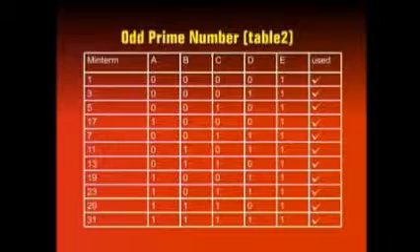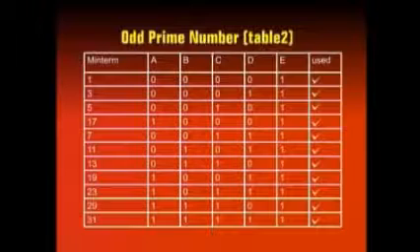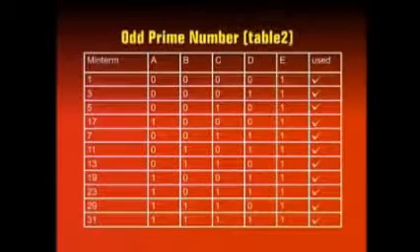Minterm 1 is compared with minterms 3, 5 and 17 in the next group. Similarly, each of the 3 minterms 3, 5 and 17 are compared with each of the minterms in the next group having 3 ones, that is minterms 7, 11, 13 and 19. Minterms 7, 11, 13 and 19 are compared with each of the minterms in the next group having 4 ones, that is minterms 23 and 29. Lastly, each of the 2 minterms 23 and 29 are compared with the minterm 31 in the last group having all ones or 5 ones.